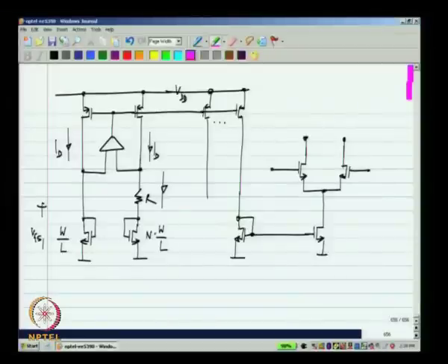Okay. And that will be independent of square law and independent of whether they are in strong inversion or not, and also it turns out it is not so affected by body effect, that is you make sure that the transistors that you use in the biasing cell have the same body effect as the transistors that you use as a differential pair. Okay. Now, how do we go about doing that?